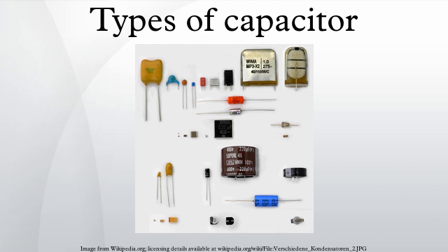As shown in the graph, the higher capacitance values fit the lower frequencies better, while the lower capacitance values fit the higher frequencies better. Aluminum electrolytic capacitors have relatively good decoupling properties in the lower frequency range up to about 1 MHz due to their large capacitance values. This is the reason for using electrolytic capacitors in standard or switched-mode power supplies behind the rectifier for smoothing applications. Ceramic and film capacitors, because of their smaller capacitance values, are suitable for higher frequencies up to several 100 MHz.